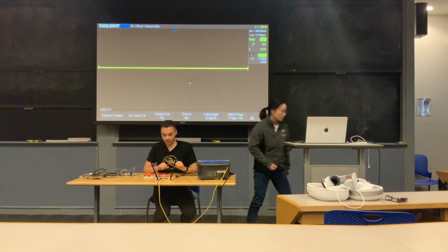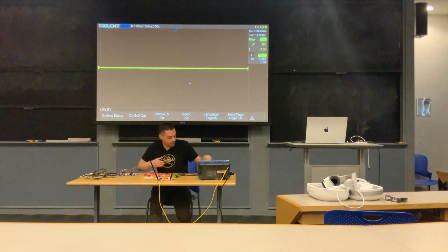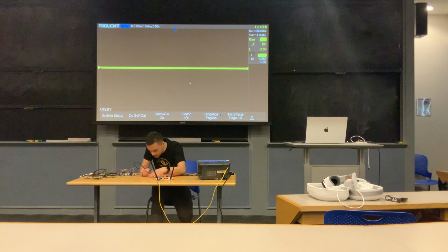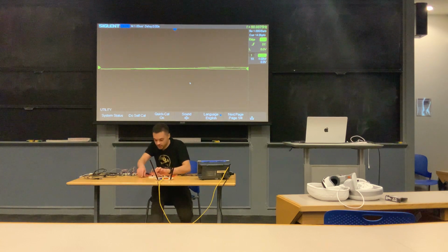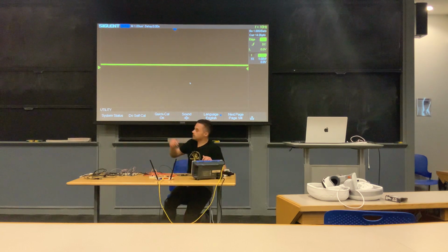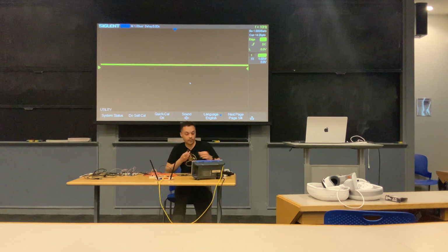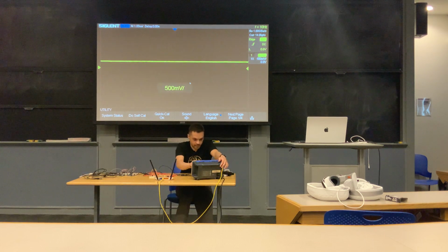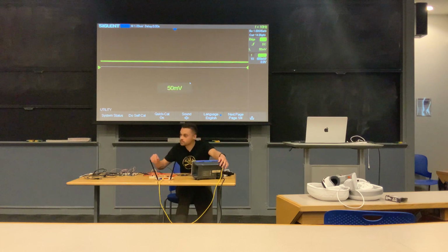It will capture. Cool. Okay, so what I'm going to do here is go ahead and connect the oscilloscope to the pins that we have broken out. So we have 2 pins here. We're going to go ahead and plug into one of them. Let's just see if we see anything interesting happening on the board here. So what we have on the screen is the actual output of the voltages on those pins. And as you can see, it's relatively straightforward, except every once in a while, it seems to fluctuate a little bit.